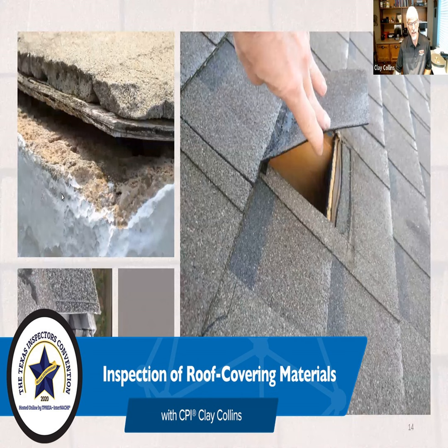Okay, last two questions. On the lifted shingles at the seams, could this also be caused by decking getting wet and swelling at the seams? Absolutely, but it could also be caused by the roof cover being installed on top of a wet vapor barrier or underlayment.